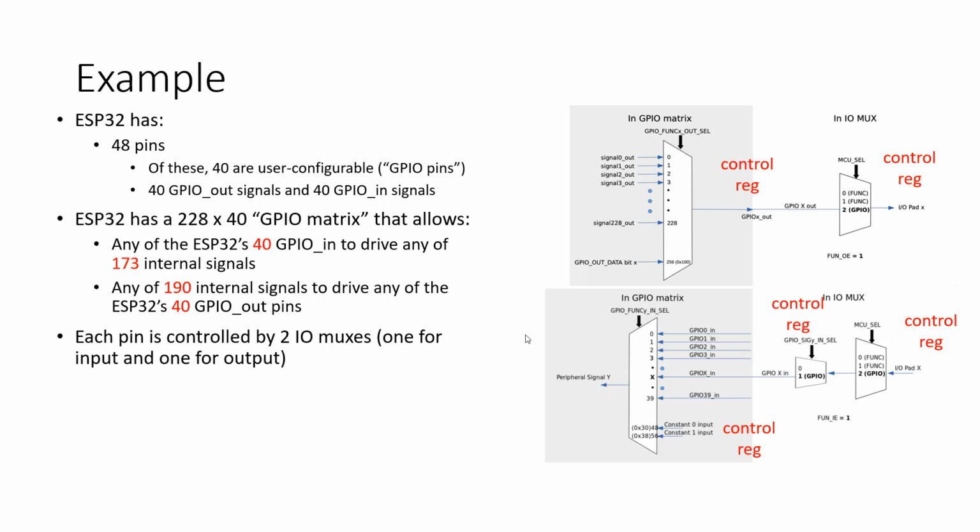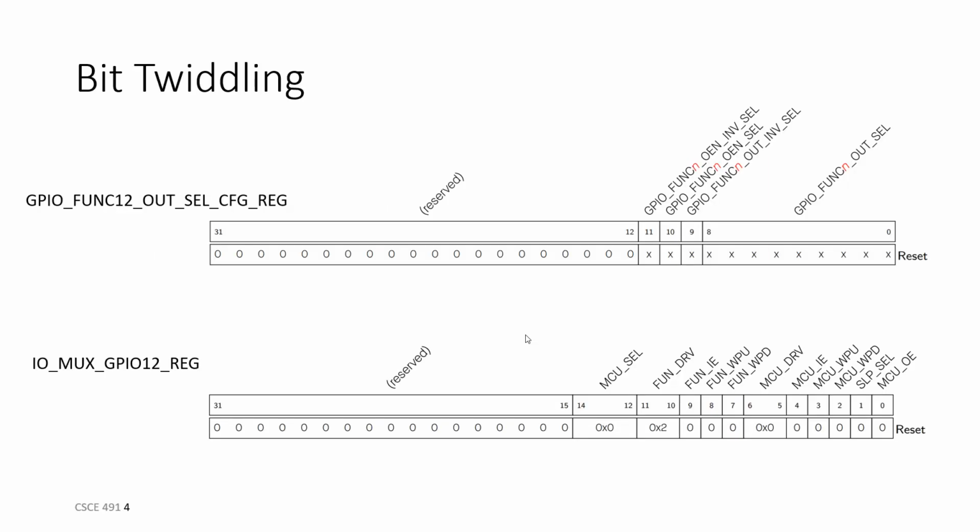Once we have it looked up and we know what it is for each pin, we can just set something up that remembers that and call that. Exactly. You just put it in your code and you don't have to worry about it again. I didn't know if it was different for the same pin, different registers based on what part of the transaction we're in or something. No, it's per pin. There's a table in the data sheet that has the IO mux settings for each of the 40 pins.